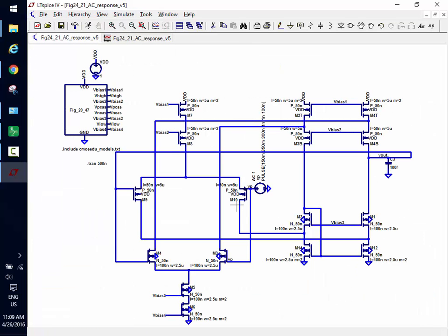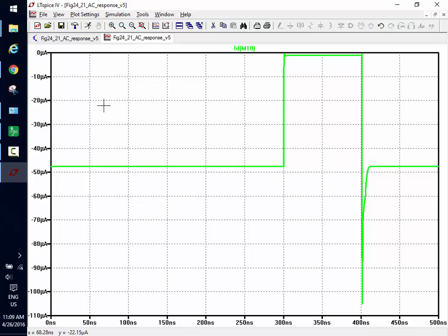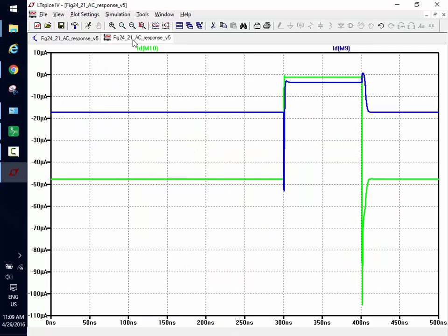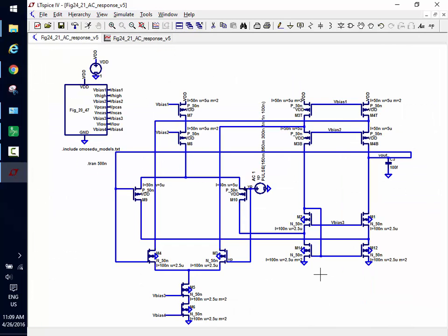But up here, when I look at the current, when it goes to 900, 850, it should go to 0, but in the other cases, it should go to 10, and it's not. It's going to 45, so I got a biasing problem. Help me find it. Does that bottom set need to be connected to the bias source? Wait, that's right. No, it's diode connected.